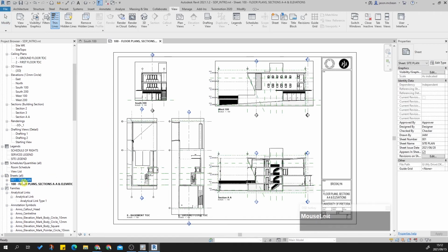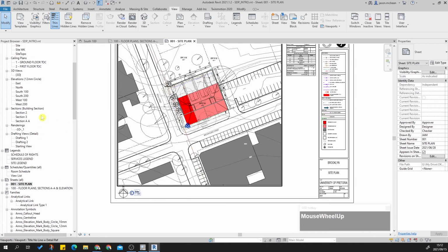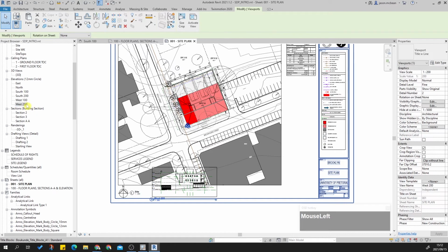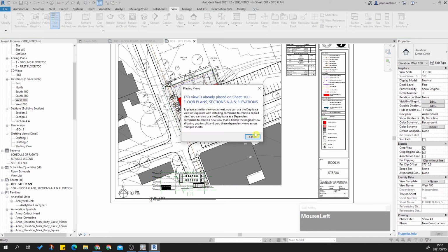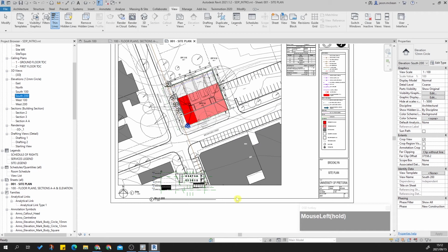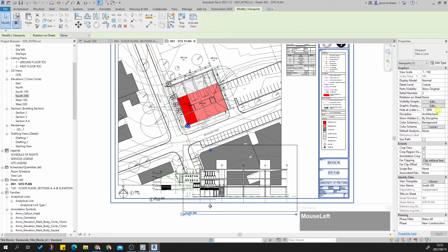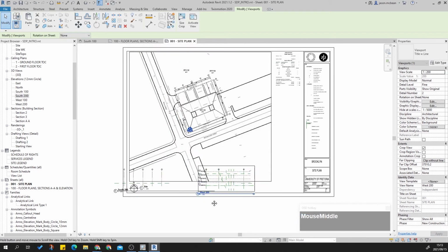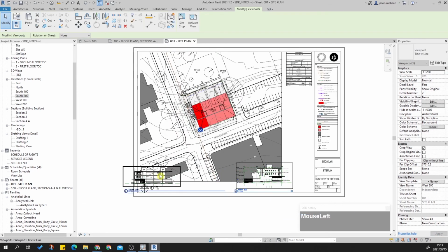Site plan. Okay, so we've got the beginnings of a plan. The only thing I need to do now is add, so I'm just adding these. Oh, sorry, wrong view. Oh, apologies. South, that's what I'm looking for here. Okay, just change that 1 to 200. That should have changed to 1 to 200. Okay, good. Okay, then I'm going to lock and align these two. And I'll put them right at the bottom. I'll put them over here. Okay, so let's just move these guys in line here.